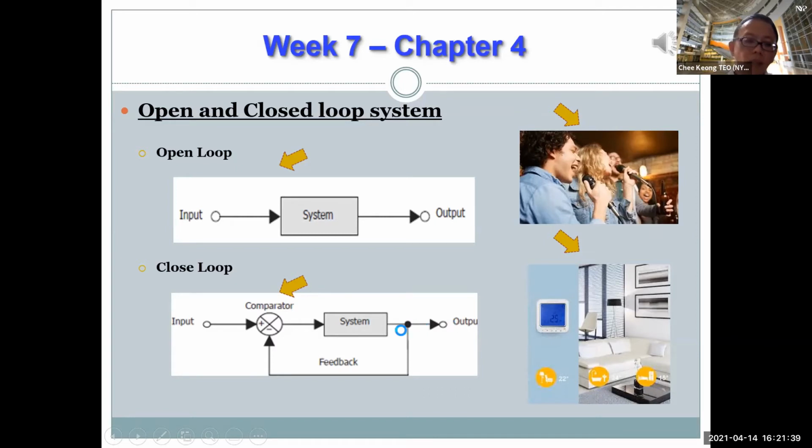And basically for a feedback system, sometimes you design it in a stable fashion, and it will settle to its final value. But if you are not careful with the design, sometimes you may get it to be oscillatory. As a result, the system will not stabilize at one point, rather it will jump up and down, which is not desirable for a closed loop system. And usually for closed loop systems, we are talking about negative feedback. Usually positive feedback is to design an oscillator. So this is not designing an oscillator, we are trying to design a stable system, therefore it's negative feedback.